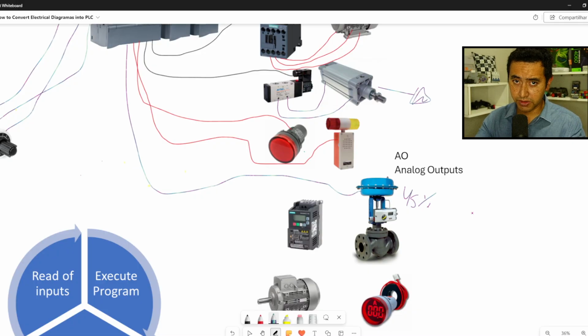Then if my temperature does not get to the set point, my controller opens more and more, over and over, then 45, then after that 55 and 65. It keeps opening more until it gets the set point. Or the other way around, it's true also: if I need a lower temperature, then it closes my valve. It's possible to do this.